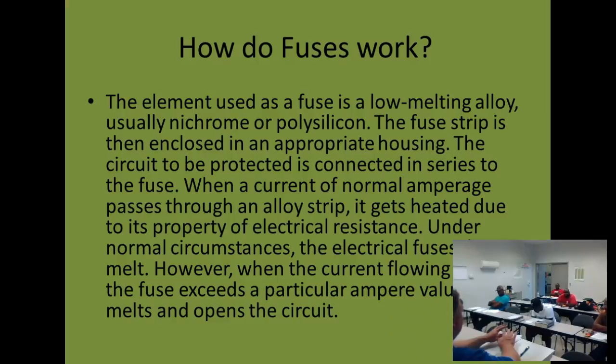Don't confuse the two. Now, if I have a closed switch, I don't want any resistance, right? That's going to be zero, right? If I have an open switch, what should it read? And everything else we're going to call measurable resistance.